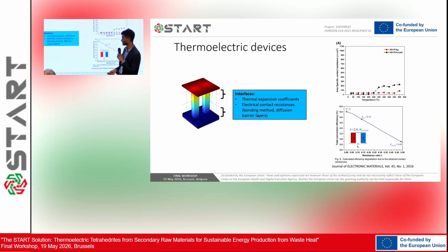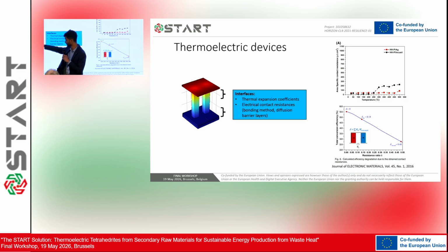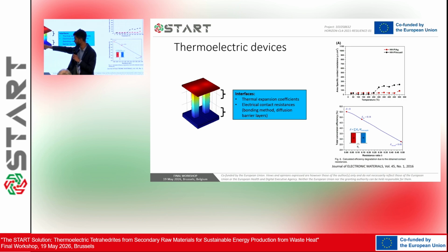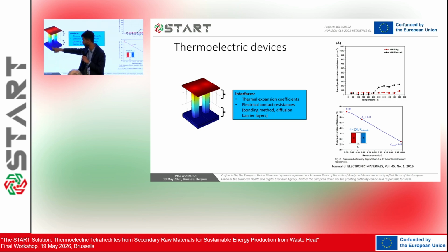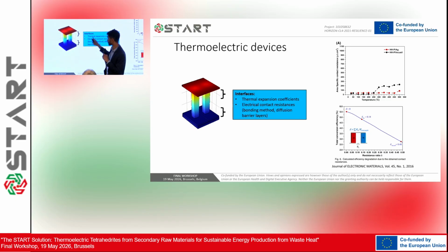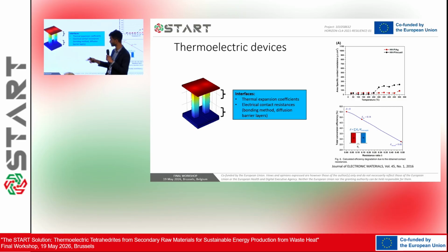Besides the material properties, there's also the interfaces. These are the thermoelectric materials, and then they're connected on the cold side and the hot side. The interfaces have to match the coefficient of thermal expansion between the active material and the hot and the cold shoes. That's something we optimized within the START project to make sure it is possible to do, as well as the electrical resistances have to be low enough.